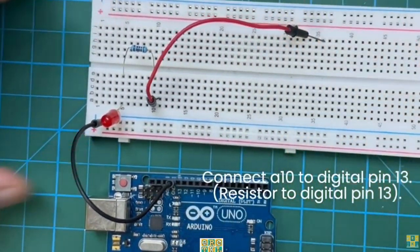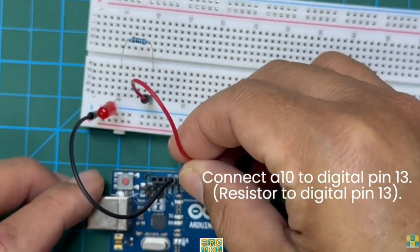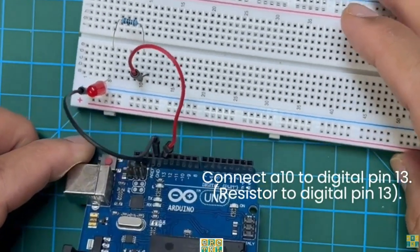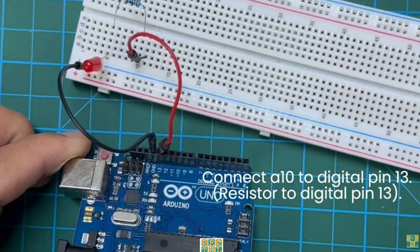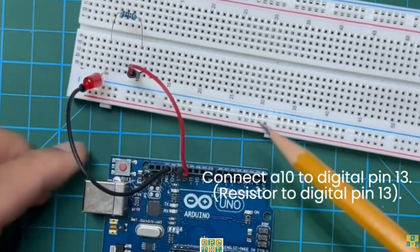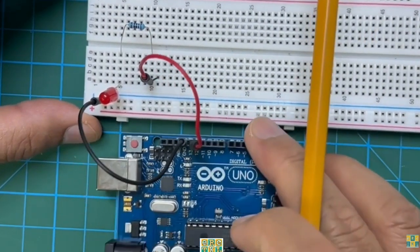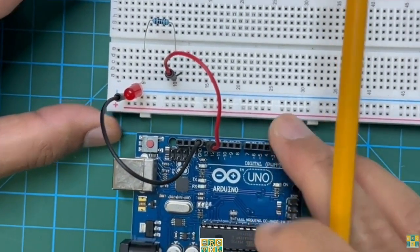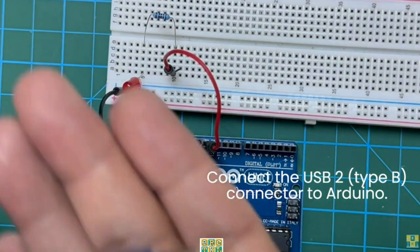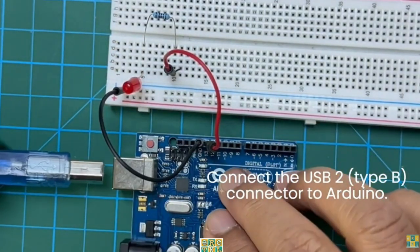I hope it's clear. So now the A10, which I chose for the positive, will now be connected to pin number 13 of our Arduino. And that's it. We have connected the negative to the cathode and the anode to the resistor and the resistor to our digital pin number 13 in series without using soldering iron. This is used for what we call as prototyping so that it's more easy for us to do the project.